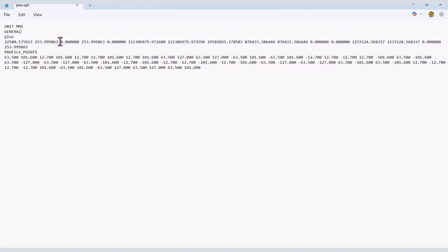So the values that we need to change is this one, and also these two. So you can see there are 4 elements where the values are set as 0. So this one represents the TB, and this is TD, and these two are for AY and AZ respectively, which are essentially the shear area.